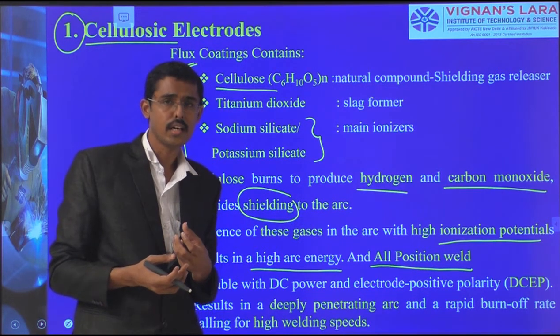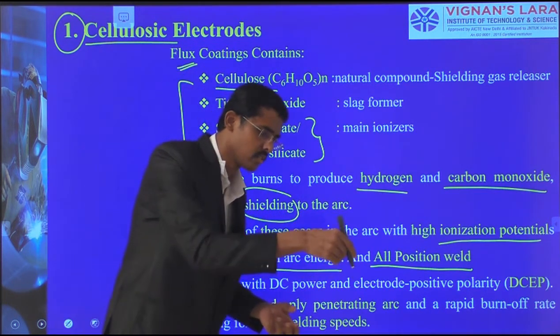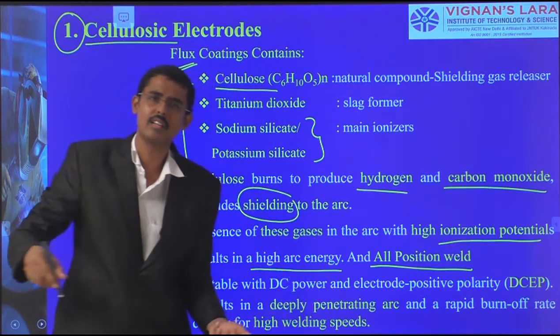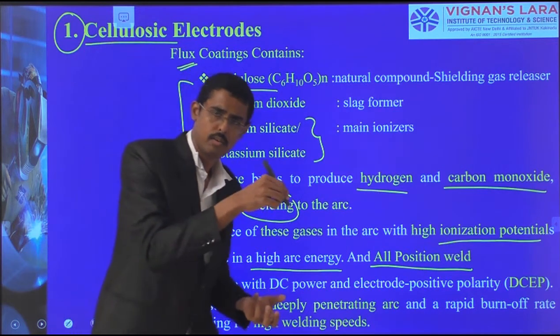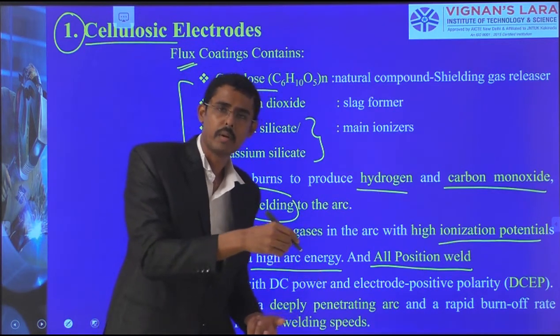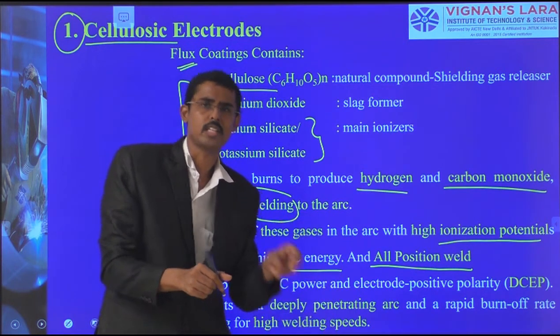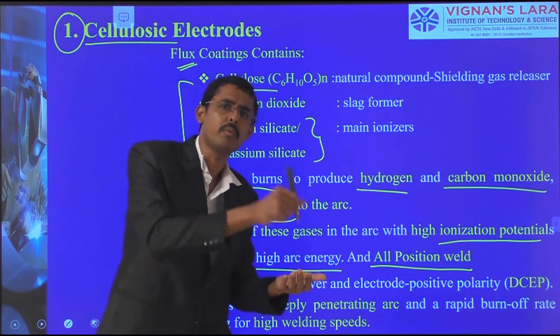More heat is generated and more melting happens immediately. Then what can we do? Even if it is heated and melted, why would you want to keep going slowly? We can move faster. The welding can be done faster. Our purpose of slow welding is to make heating at a specific location. If it is heated, melted and deposited, why keep our hands there itself?